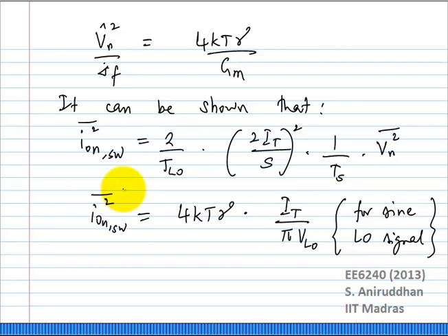Now the first thing which should strike us is that this does not seem to depend on any device parameters. Right? It seems like this noise seems to be independent of the switch, and it depends only on the tail current and the LO amplitude. Okay.